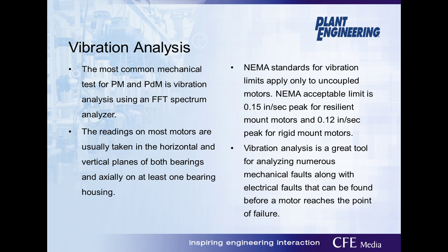I recommend always taking vibration readings of the motor coupled to the driven equipment first, for this can help pick up any signs of misalignment, coupling wear, or even unbalance of driven equipment.